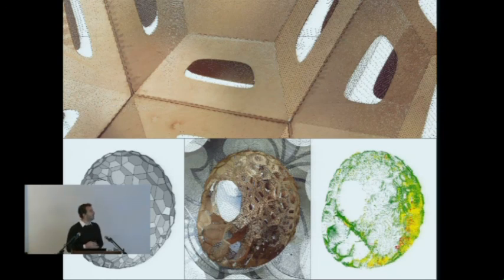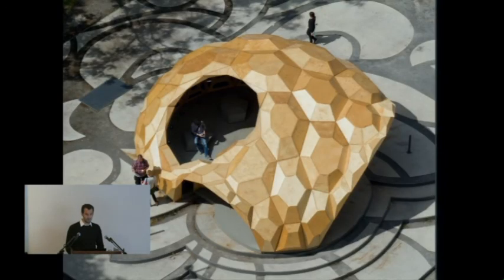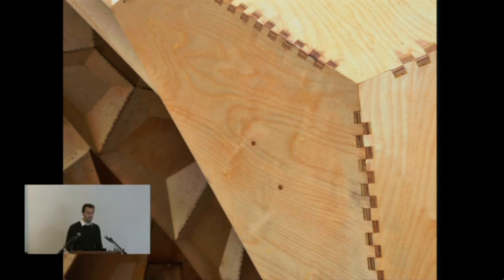So I think on that image on the right, on the top, you can nicely see the resolution of these laser scans nowadays, which is almost like a 3D photograph. And on the bottom, you can see a mapping of the deviations between the computational geometry and the actual geometry. So the resulting lightweight modular wood shell quite nicely demonstrates both the structural capacity and the architectural potential of a system that exclusively consists of extremely thin plywood plates that are connected only by these robotically fabricated finger joints.